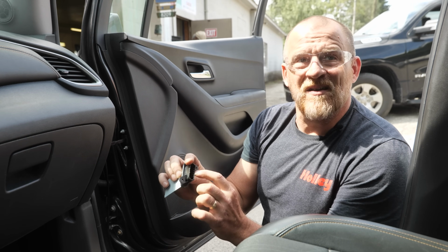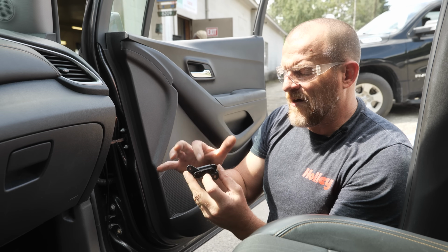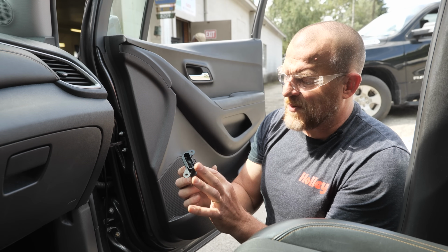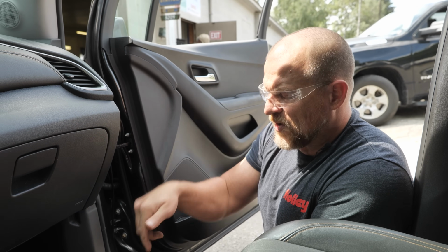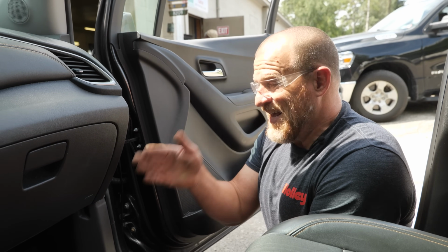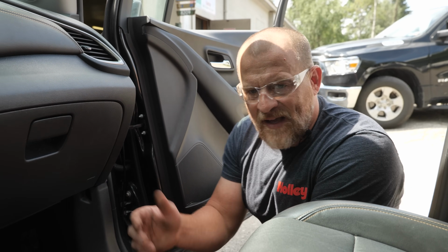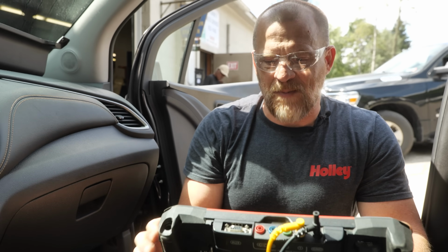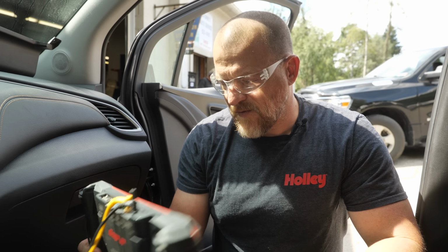This is suggesting to me a terminal contact issue, or just poor design of the part where it's damaged up in here. But you're talking airflow is another one, poor terminal contact, or the blower motor itself drawing too much current. It is on a 40 amp fuse, so it's going to have a lot of current flow. I can't give you a spec on what the blower motor amperage should be, but we're going to look at it, just covering all our bases. I think the motor's fine based on what it sounds like.